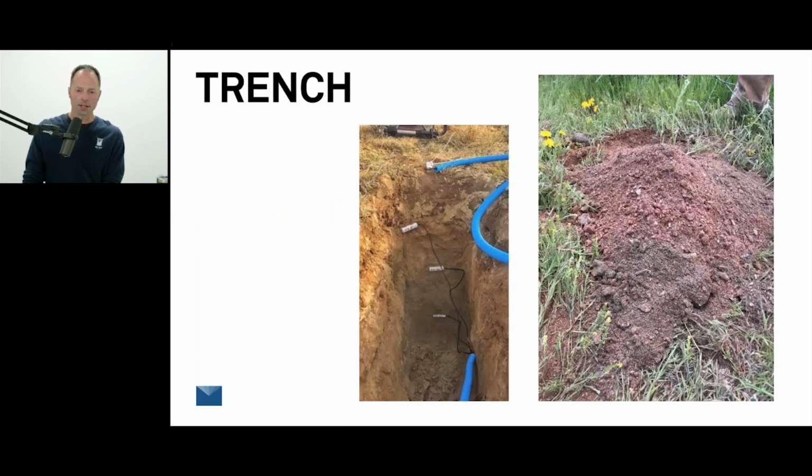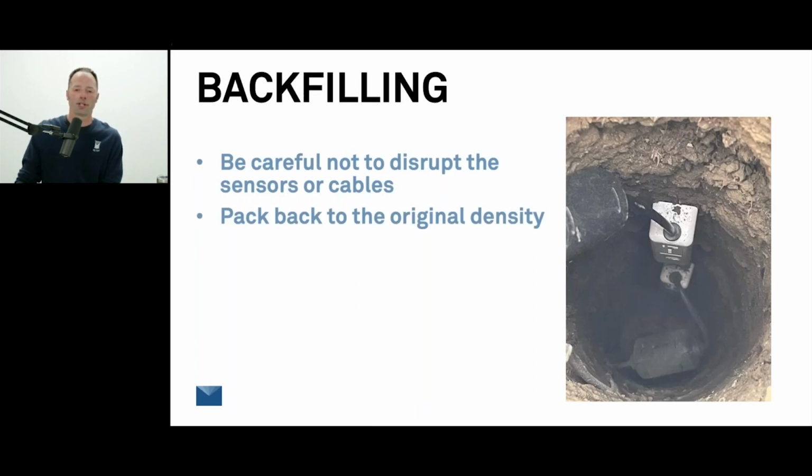And then at the end, you want to check your sensors again. I showed a screen on a ZSC Bluetooth reader earlier. Check it again. Make sure you have not dislodged your sensors, because that's the worst possible thing that can happen here, is that you're throwing dirt in and packing around. You want to be really careful when you're packing dirt around the sensors to not knock them out of the side here and then wind up with an air void here, which will be difficult to explain later, or can just add extra noise in your data set.